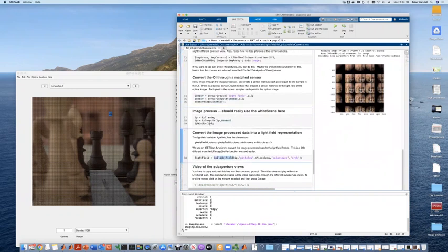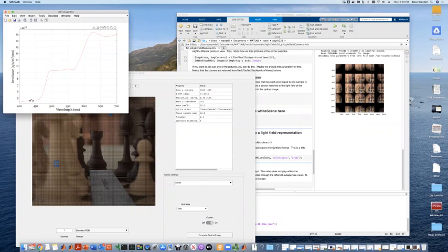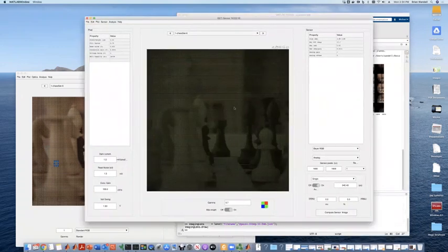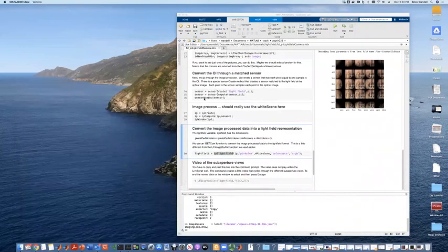So here, at this point, we've lost our wavelength information. I was just supporting your point that when we're in the optical image, if I look at some little piece, it's got wavelength information. Here's wavelength, and here's irradiance and so forth. So this is still a spectral image. But by the time you get to the sensor image, this is not a spectral image. This is now an image in terms of electrons or volts at the sensor. So we've lost the wavelength information when we go from the optical image into the sensor image.